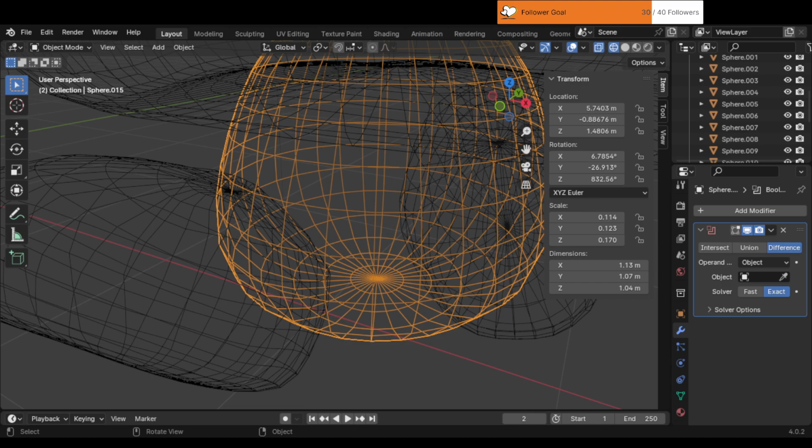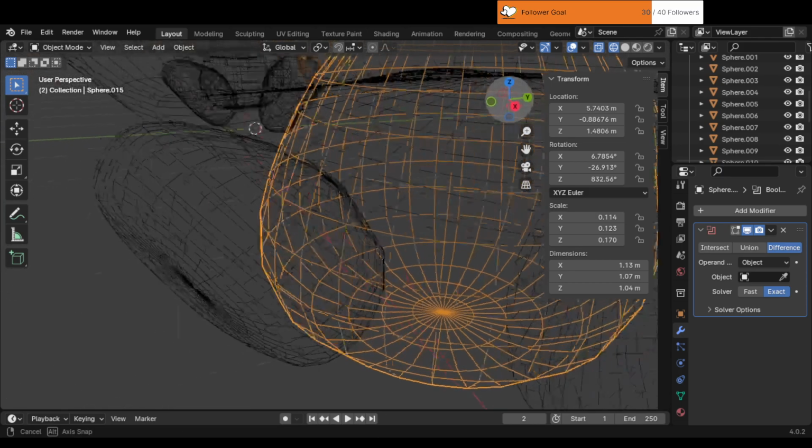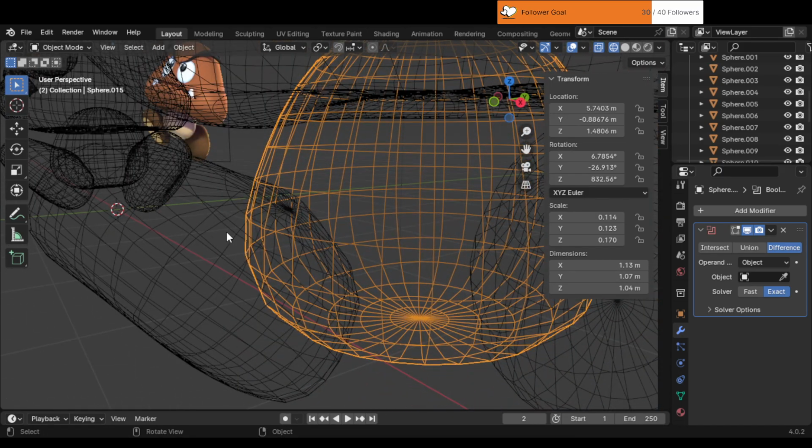Yes, you can perform Boolean operations to modify the shape of one item using another item and then delete vertices from the modified item. After that, you can join the meshes and then work on merging them to create a seamless connection or tube them together. Here's a step-by-step guide on how to do this in Blender.